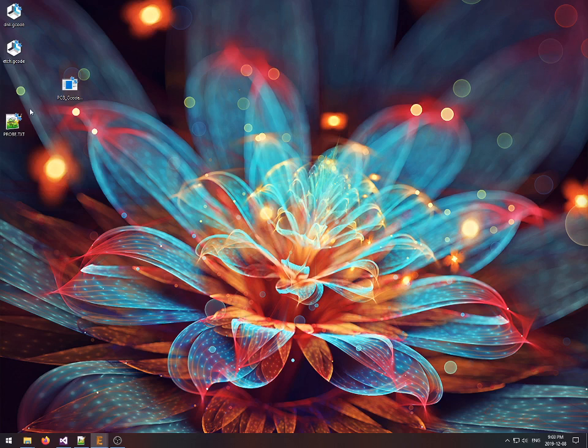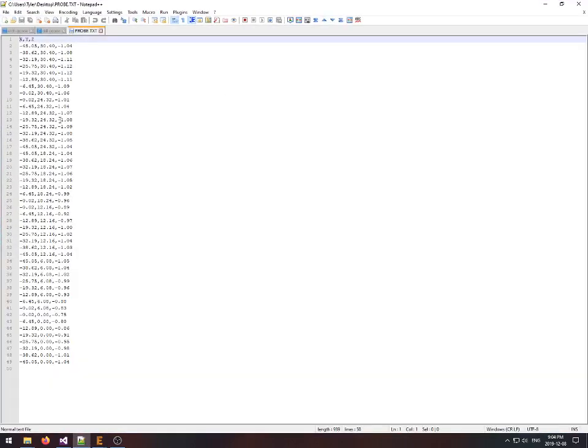Now we're on to the etch Gcode. One of the things I've noticed with PCB blanks is that they're not level. So I have a function on my PCB milling machine to generate a probe grid. It'll go around, it'll touch the PCB in several points in basically a grid, and it'll spit out this file. So you can see it's probing.